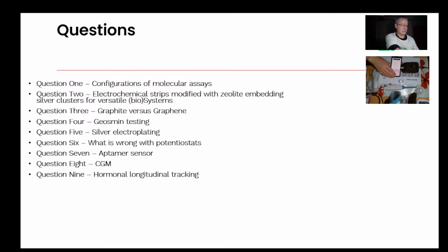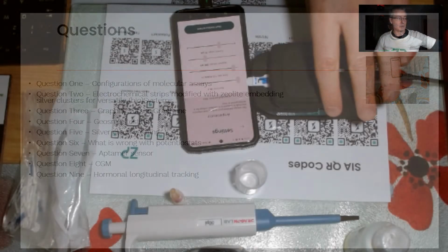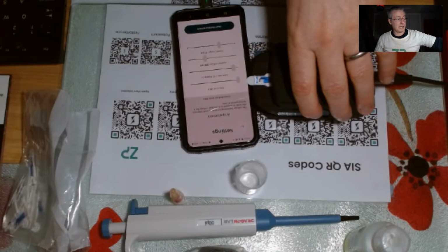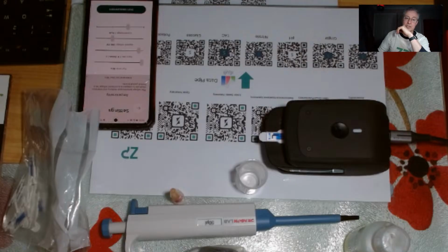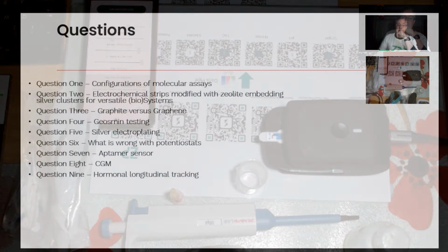And potentiostats often have multiple applications: capacitors, batteries, corrosion, and fuel cells. Some of them are also okay for biosensors, but a potentiostat that's good for batteries and good for biosensors is not the same potentiostat. They're very different instruments. So this potentiostat in particular is really tuned up for doing biosensor development, and because we've got a cloud system attached to it, I can actually process the data and turn that data into analyte concentrations as well. All right, with that said, let me go forward a little bit faster.